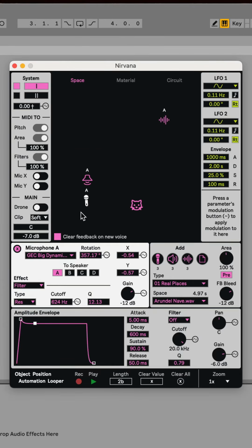Other things that might affect that tuning are the microphone and speaker model and distance. So like I said, just go back and forth to find it. If you're going to do this, I recommend using a resonant bandpass filter, but you can also get away with a low pass and other things. Just make sure you turn the resonance up enough so that the fundamental of this filtered frequency takes over. You'll notice certain situations will do it better than others, or it might fall apart at different octaves depending on the microphone and speaker and the feedback situation. But if you're just doing something simple like this, it should work pretty okay.